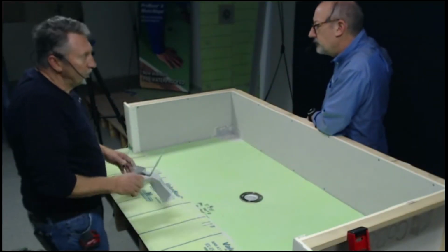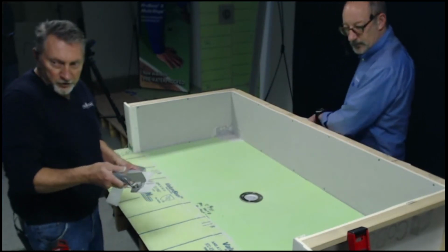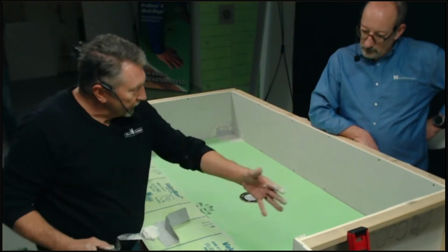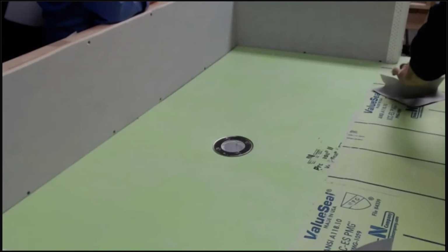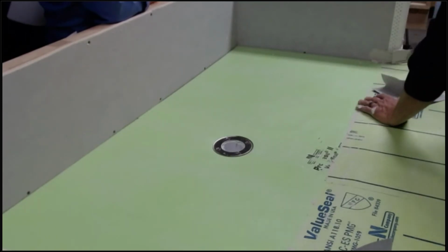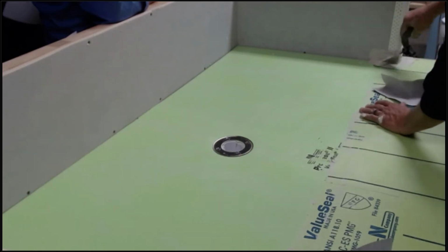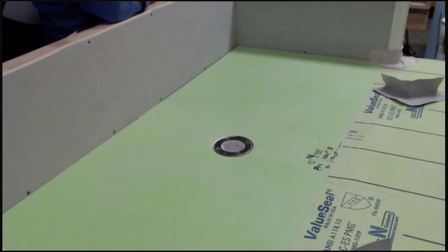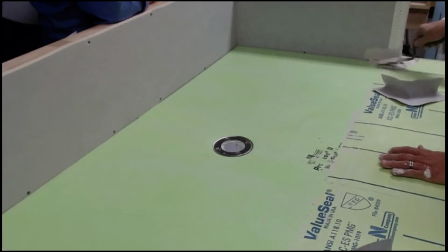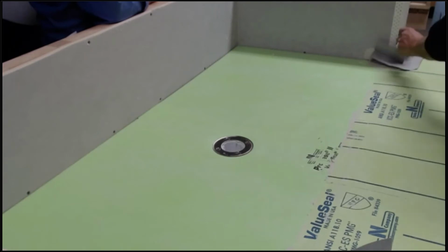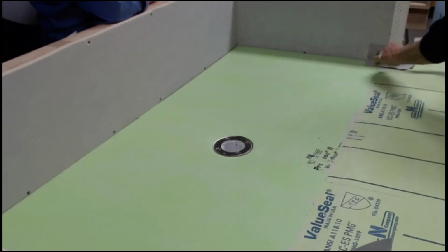So what are you doing for the outside corner over here? So for the outside corner, go ahead and put it on the other end here. You're going to make that transition from the dry space using that outside corner right here. Again, you'll just put modified thin set. You can put it on the corner or the base, it doesn't really matter which way you want to do that. Make sure I have plenty there. And just place the outside corner here. And again, just tool it in.